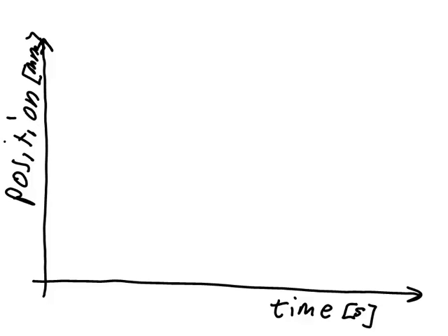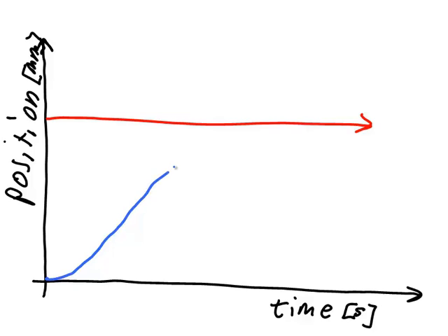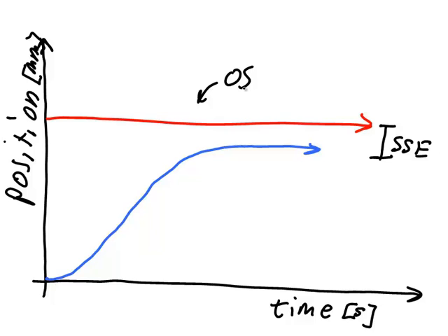Now here we have some commanded position, and we would have some response position, the actual motion of the joint. With our small Kp value, it's likely that the response we see would look something like this. With a small Kp value, it's likely that we would see a large steady state error, no overshoot at all, and a very slow rise time.